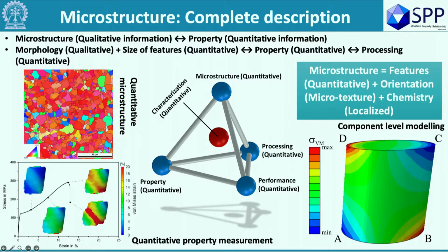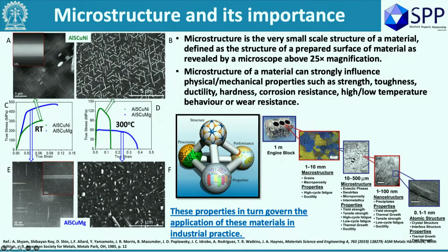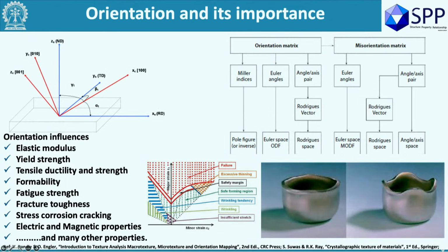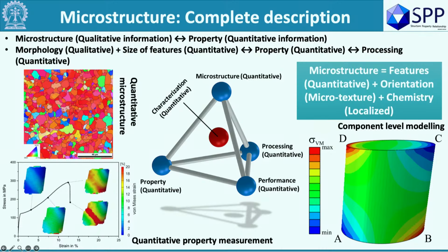Microstructural level we normally consider based on a length scale. Now the definition of microstructure has also gone to many different length scales. So the aluminum alloy that I showed you, for that it's not a microstructure, rather it should be called a nanostructure, because that's where it controls the properties. So the definition of microstructure is still basically based on the length scale itself. So EBSD was able to give you orientation at that length scale. That's the first advantage that we saw.